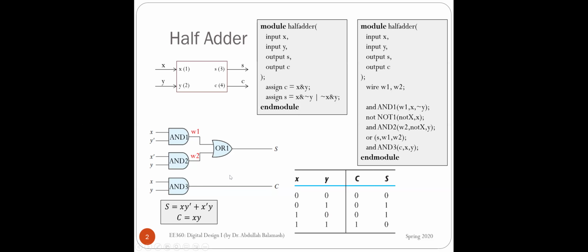And you can write a module for the circuit like a function. And you can describe this circuit using Verilog, using something called module. A module is similar to a function. You need to define the inputs and the outputs, and then you need to find how the circuit is constructed. Okay, let us start with this module. Now we'll have two different ways to do that. This way we use the logic gates directly, and this way we use the Boolean functions. We call this structural design, we call this data path design, but both of them reflect our design. So it's okay to use this one or this one. This is similar, but let us see both.